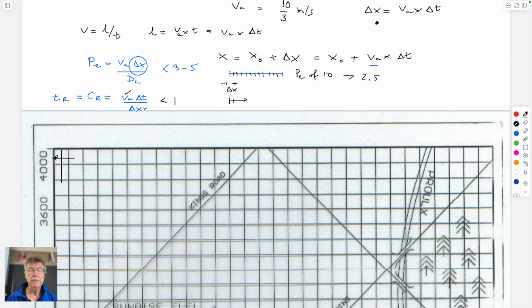So if you double the grid spacing, from a one-dimensional grid you'll double the number of equations, if it's a two-dimensional grid, you'll multiply it by 4, and if it's a three-dimensional grid, you'll multiply it by 8. So there's a cost that comes with making the grid finer, because it'll take longer to solve your problem.